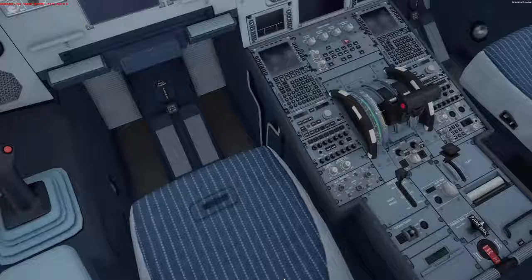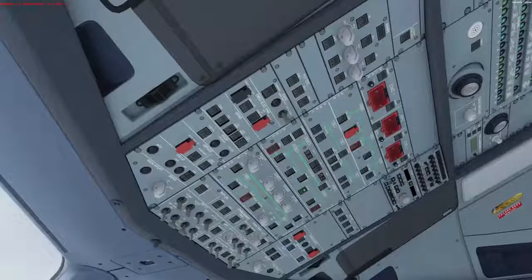The process we follow is overhead panel and switch both batteries on. We then need to switch on the nav and logo lights, so anyone outside the aircraft knows there are actually people on board.